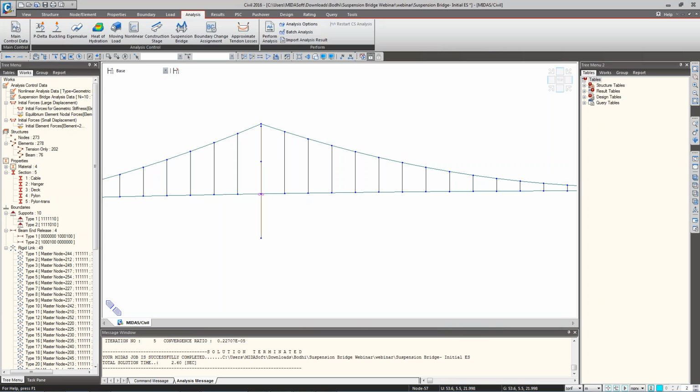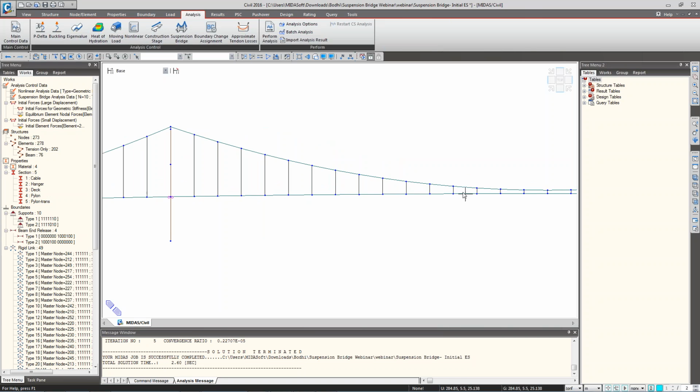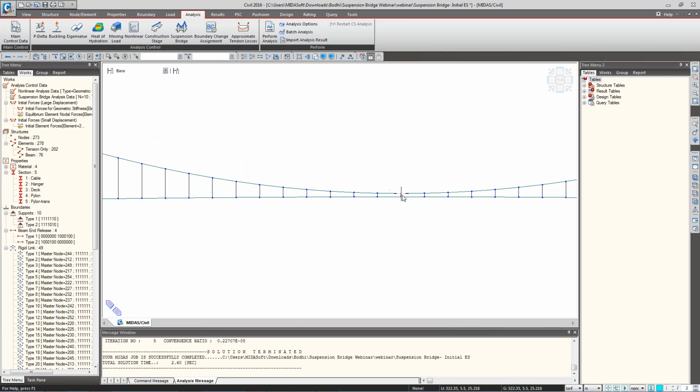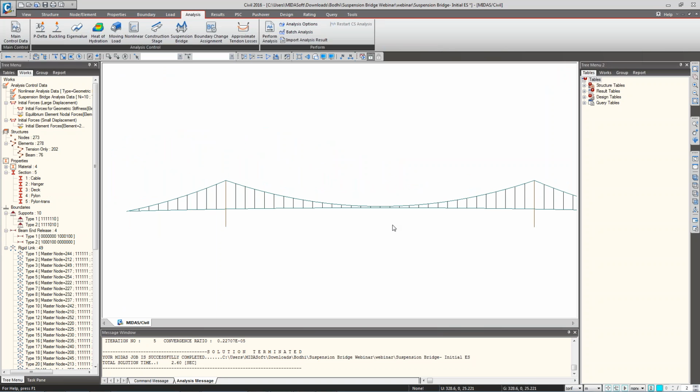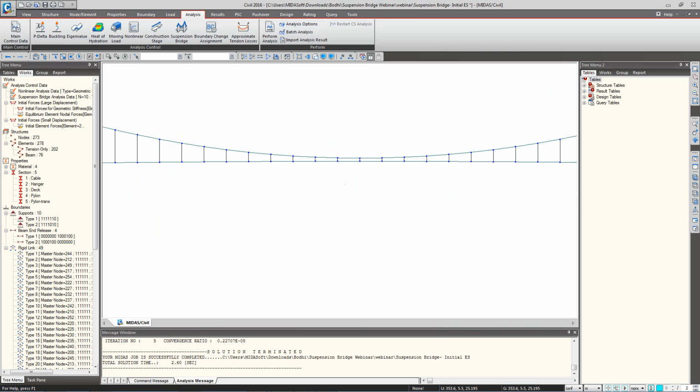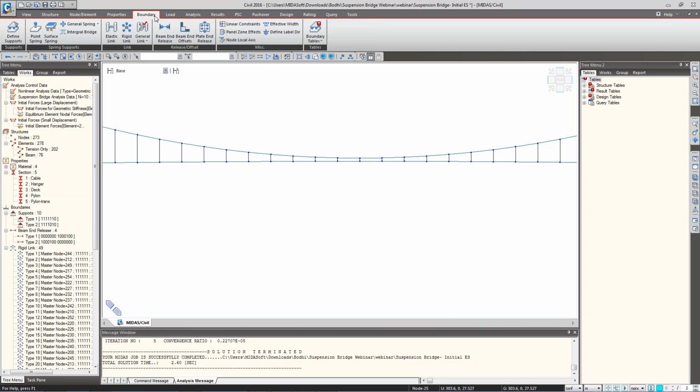so once you are done with that, you have to sustain the cables now in the horizontal directions. You have to restrain any forces for the cables in the horizontal directions. So you need stay boundary conditions in here. For the sag points, what we can do is go to boundary and go to elastic links.